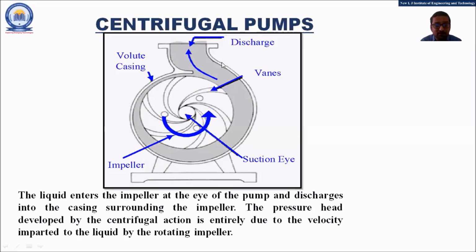So friends, if you observe the image of the centrifugal pump which is given in your textbook, if you observe the different heads, the limit of the suction head is fixed. There is the boundary in the suction head, that is HS. But if you observe technically, there is no boundary in the delivery head. In the delivery head, 2 arrows are mentioned in your textbook. That means the delivery head is dependent on the pressure head generated by the centrifugal pump.